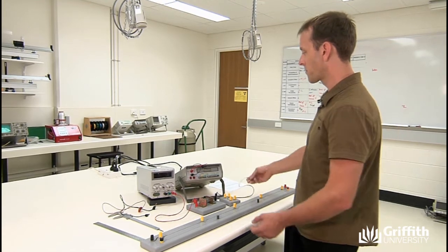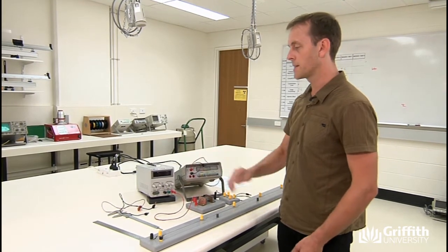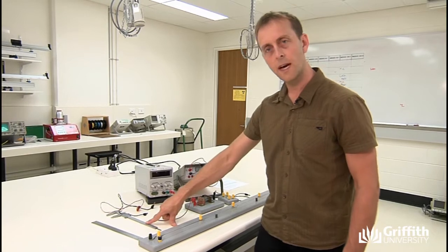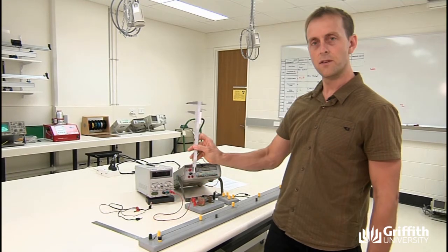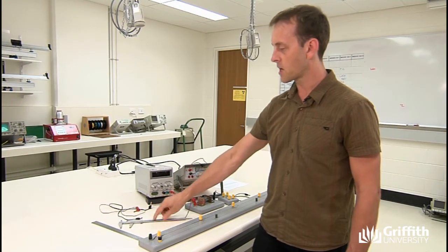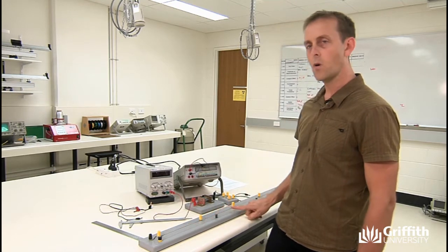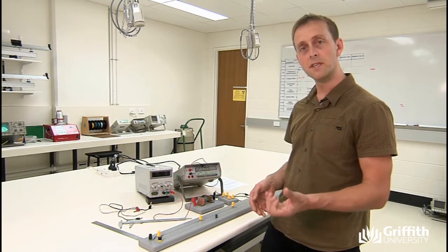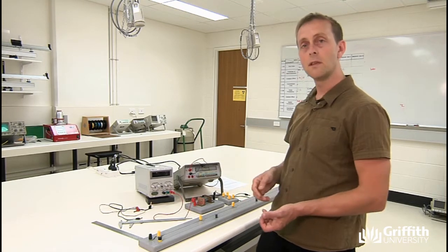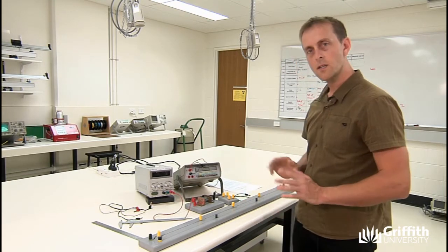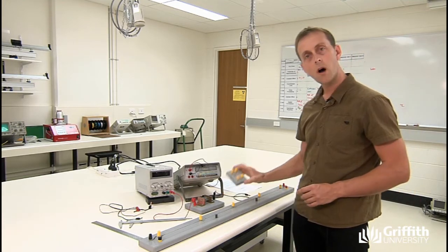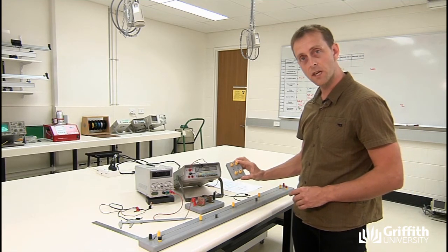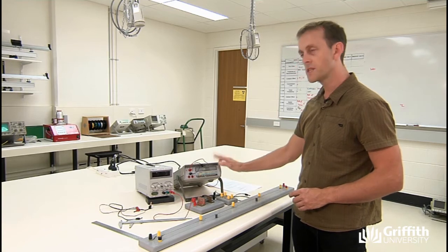You've got a bunch of different probes around the place, just wires. You also have a vernier caliper. You're used to using one of those by now, and that's going to be used to measure the diameter of the wire, because that's an important part in our equation relating the resistance to the resistivity. We're going to use our high quality 1 kilo ohm resistors to measure the accuracy of this multimeter.